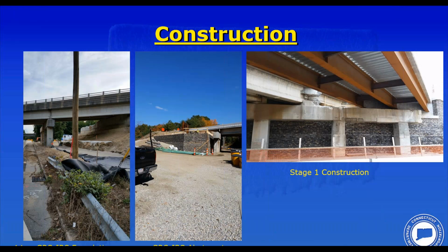However, we want to use GRS-IBS, which is considered an ABC method. And why is that so? Because GRS-IBS bridges can be built very quickly, and they can be built underneath existing structures fairly easily. The contractor was able to build, and these photos on the left show the beginnings of the GRS-IBS footing going in, which is essentially a reinforced soil footing. It's not a concrete footing.